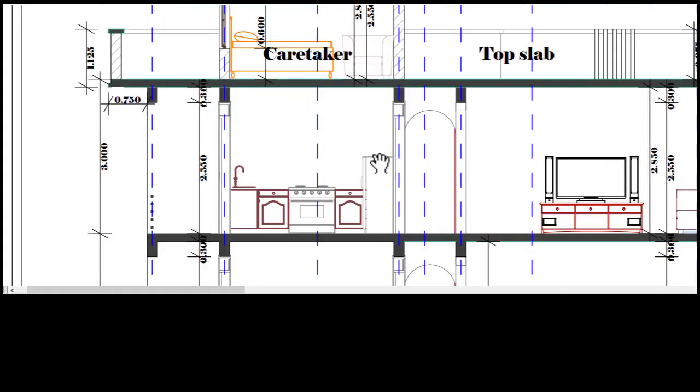Using the grids that we had done previously, from 9.2, beyond it, it's 750 to the external face of that particular point. So we need to take 9.2 and then add the extension of 750 to it. Let me get back to the section again.